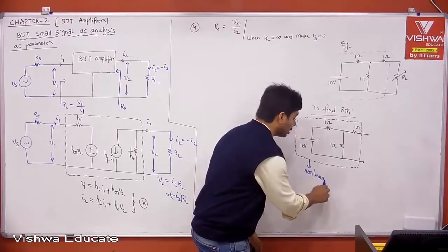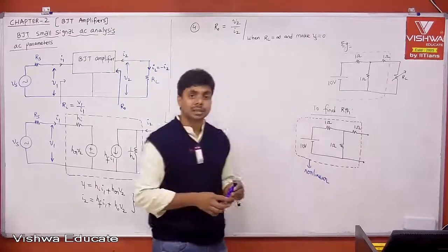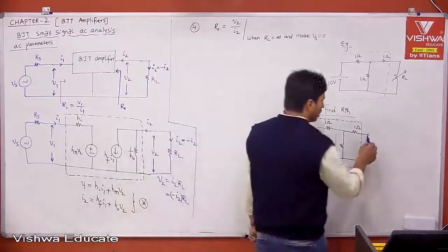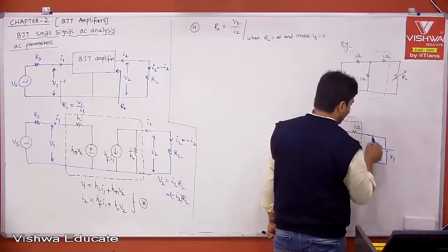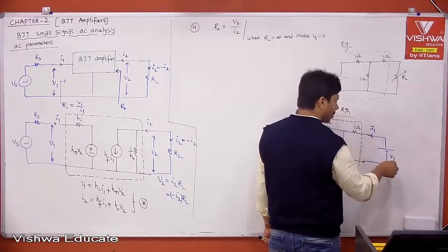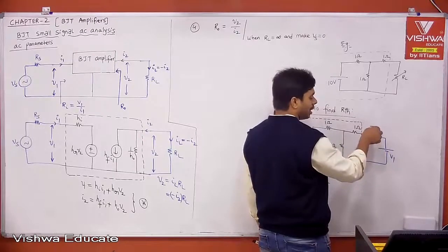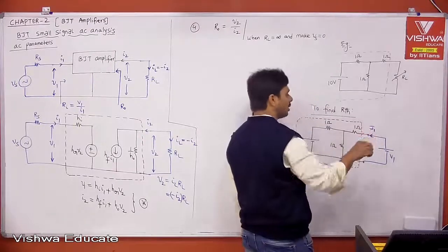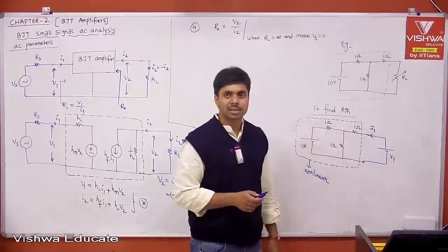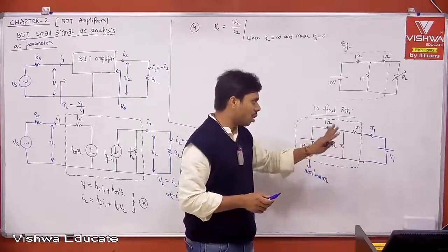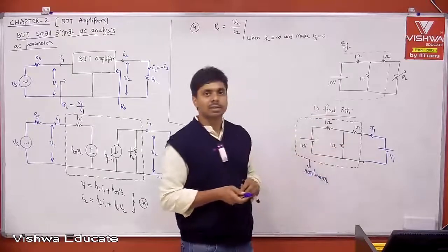then we should not define static resistance. What is static resistance? Let us say I am applying the voltage V1 and I am getting some current I1. Then V1 by I1 is not the resistance seen between these 2 terminals, because that is what your static resistance is. Static resistance is not true for non-linear networks.